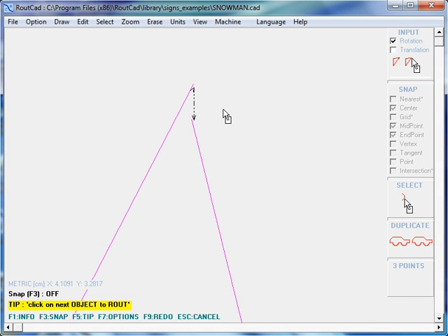In the config file you can define how big the gap is that you want for continuous routing. In this case, the gap is so small, and for the time being, the continuous routing in the config file is set to half the drill diameter.